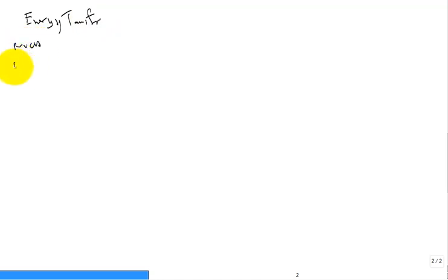So we have the process from 1 to 2, from 2 to 3, from 3 to 4, and 4 back to 1. Those are the processes. And then you can describe them. What was the process? Well, it was adiabatic compression and reversible, hence isentropic compression. You can make some notes if you like. I don't have a lot of room here, but I like to do that. It's just reminding me what's happening during these processes.